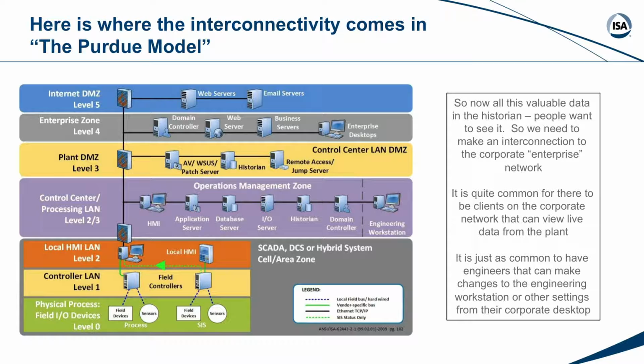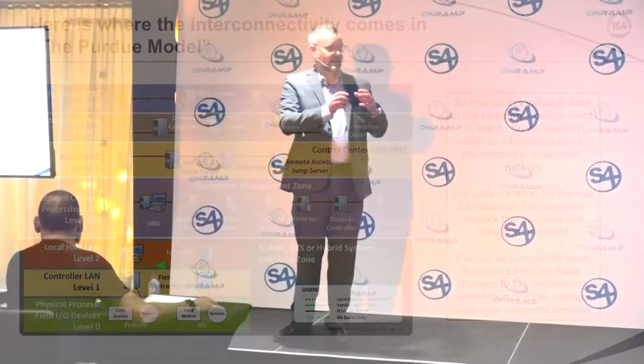So you would have individual I/O racks, input-output racks, where you're wiring dozens maybe of these things together. And then those little input-output subsystems get networked together through a digital bus like Foundation Fieldbus or Profibus or something like that to go to a controller.